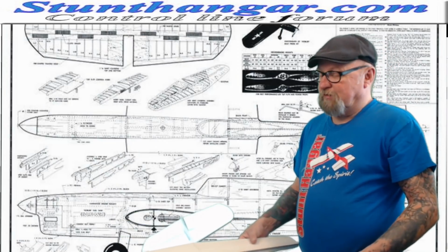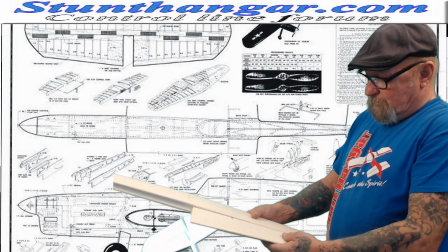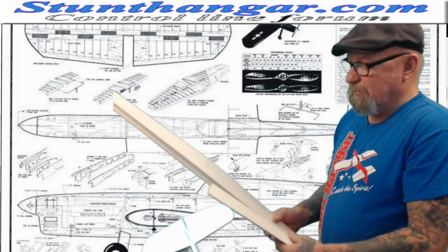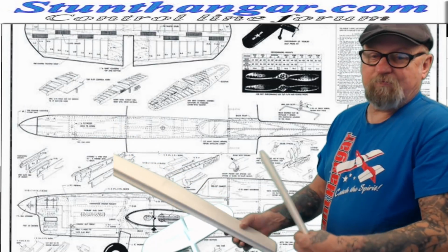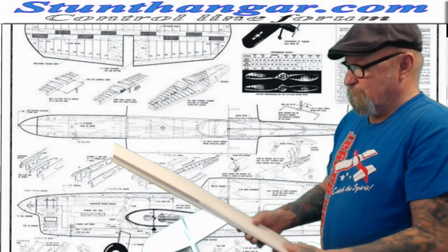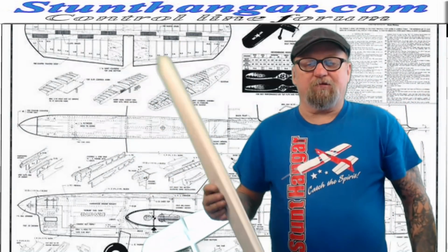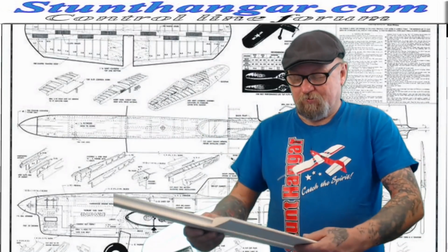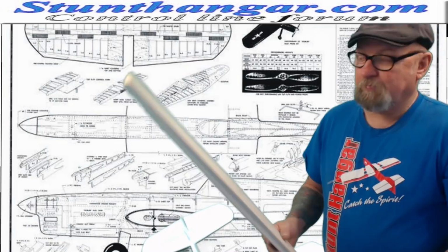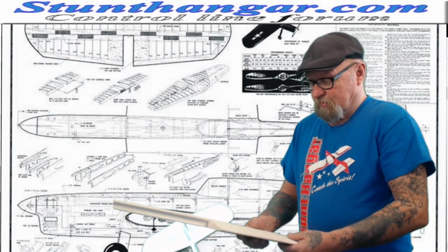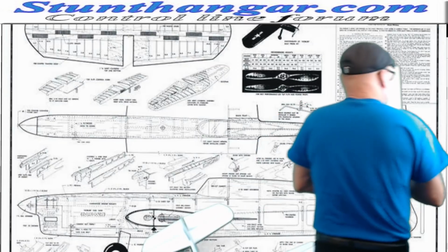Half the distance of the wing. So you've got 3.5 at the root, and let's say I really want a sweepy looking elevator stabilizer, so I want 1.25 inches at the tip, or I want 2 inches at the tip. But I would suggest that you try to keep as much surface area on the stabilizer as possible. Not only that, it helps the airplane go around the corner. Anyway, on to the next thing.